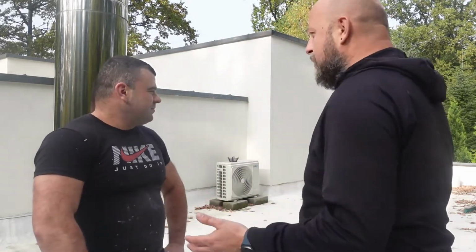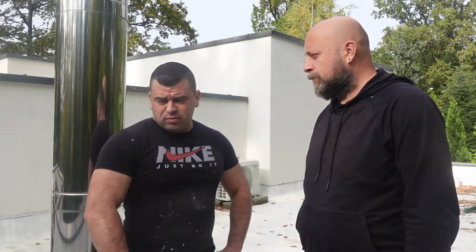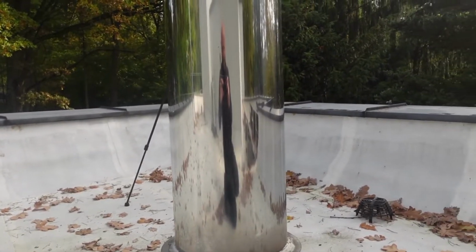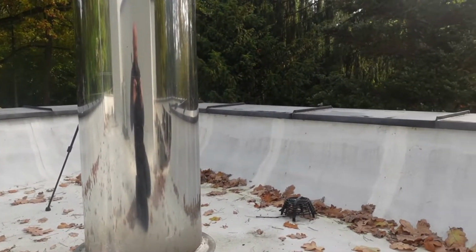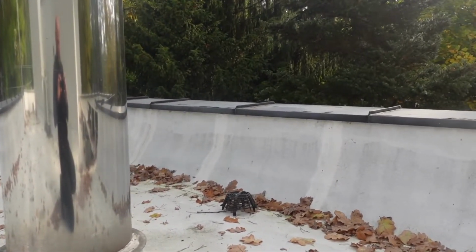Why did the flooding occur in the first place? The flooding occurred due to improper installation of the roofing material on this roof. Simply the roofing felt was poorly done, overheated in some places, underheated in others. The water got in, generally all the edges, you could say, delaminated. Water got under the felt where the styrofoam insulation is located. It turned into a lake.